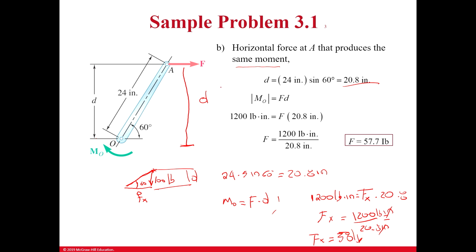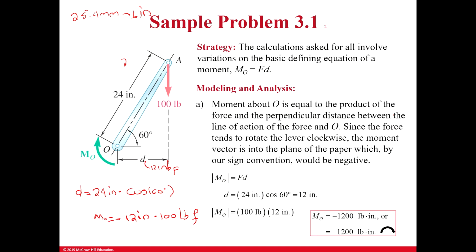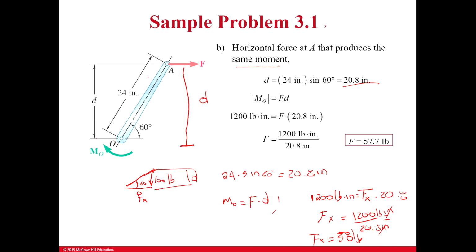So notice that that force creates the same moment with 58 pounds, which is not very much, versus this force creates the same moment with 100 pounds. So if you were trying to use this tool, this force right here, you'll have to be pushing harder than if you go this way, if you just try to push from this force right here. Okay, so the moment is the same, but the forces are different.